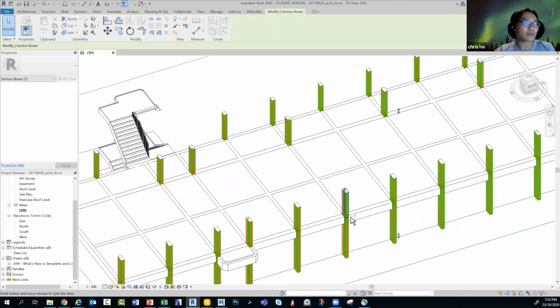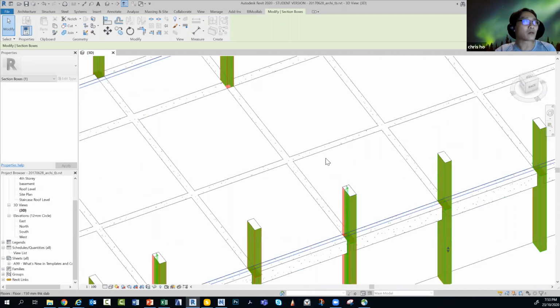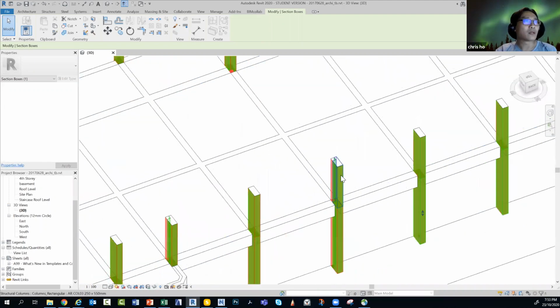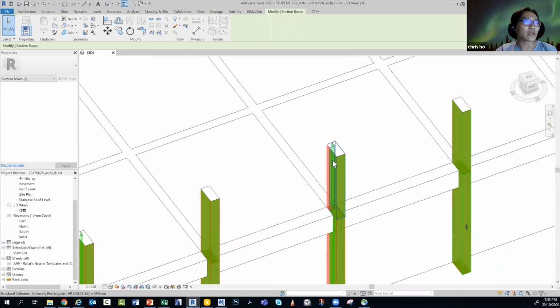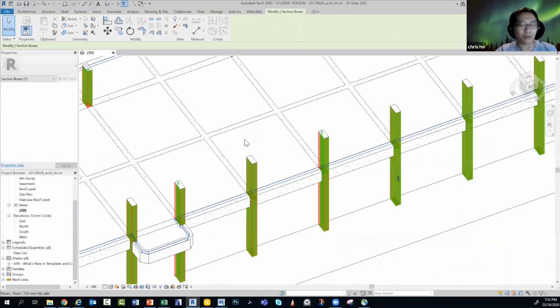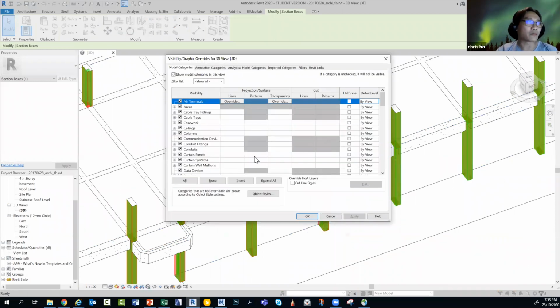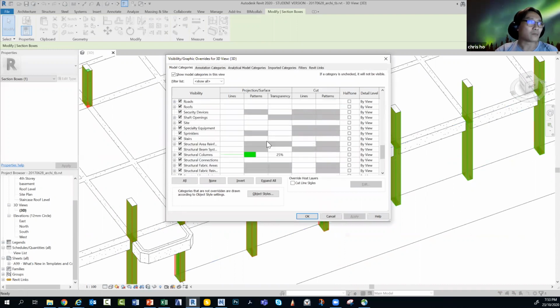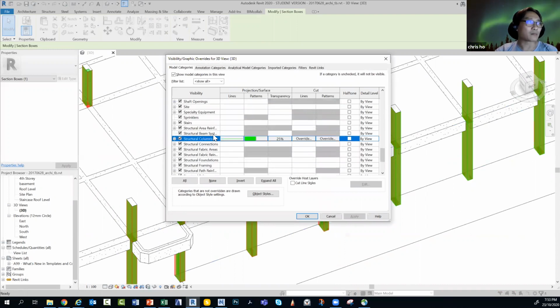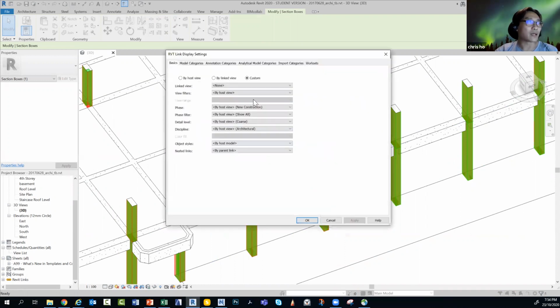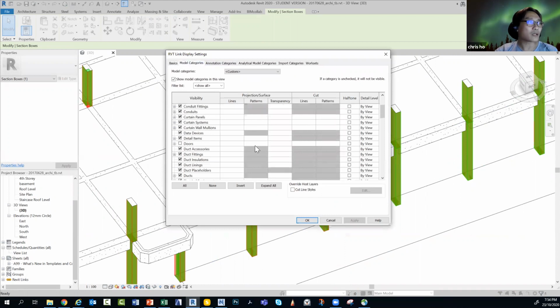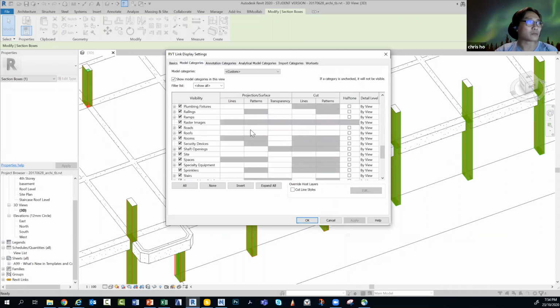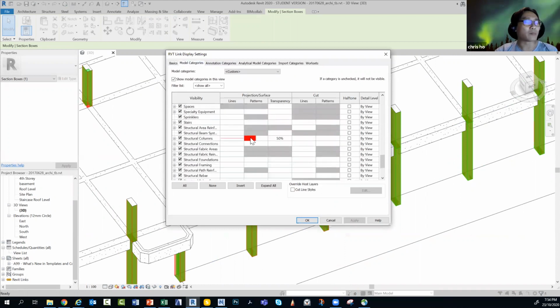Actually, Revit itself can also do interference checking. We can also do visual checking by coloring the different models in the visibility graphics. Sometimes we can do very preliminary checking. For example, I color my structural columns green, and whatever links I bring in from my structure model, I change to red.